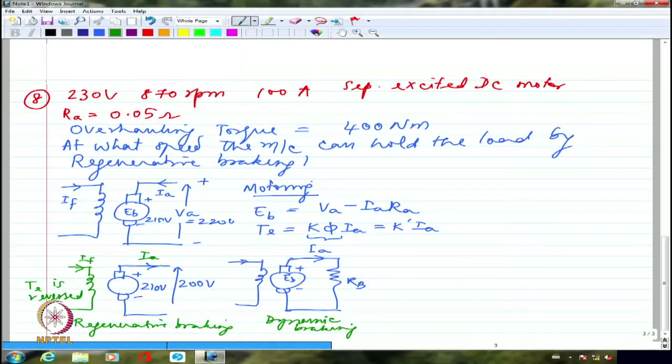That is not efficiency. If you are talking about quick stopping, maybe that gives a quick stopping, that's what you think. But here also if I put a small resistance, it will give me a very good stopping control. Right? Electrical braking gives you extremely fine control. That's why electric vehicles will have an excellent braking mechanism, if it is designed properly, of course. So this is regenerative braking.